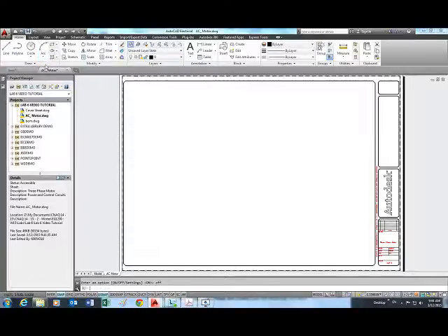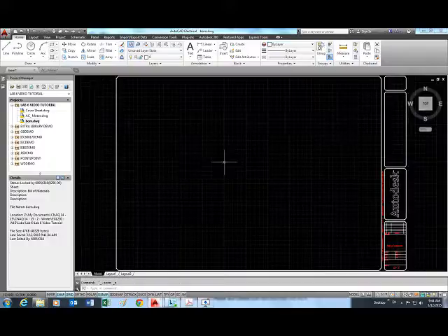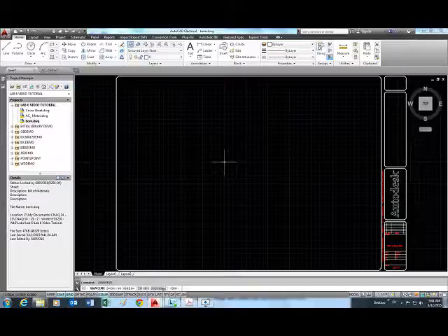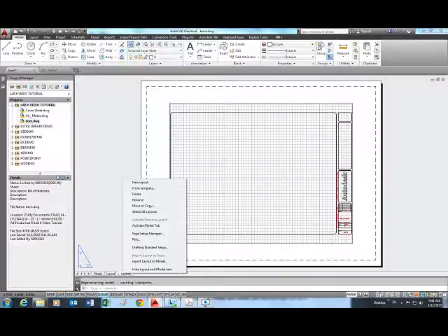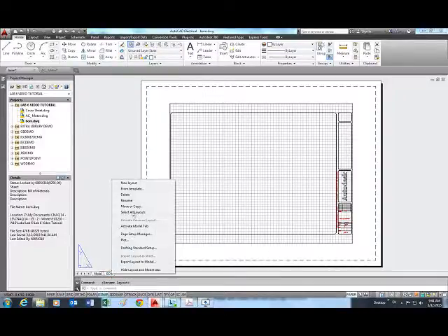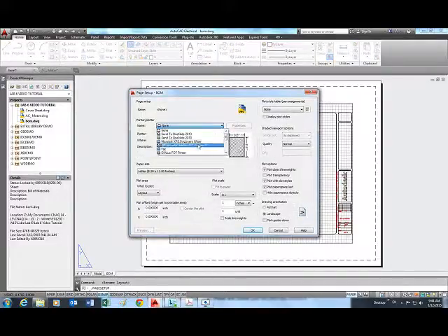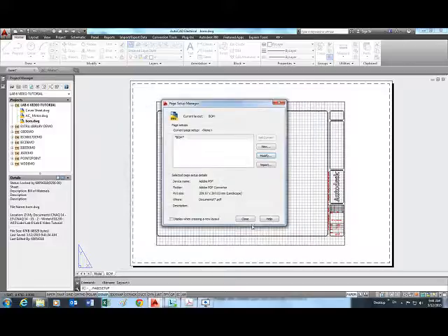So it's a good idea to save every so often to make sure that in case something goes wrong in AutoCAD that your work is not lost. Okay, let's go to BOM drawing, say nav cube, again off from the model tab, delete the extra layout tab. Let's call this BOM, enter, right click, page setup manager, modify, again PDF, Adobe PDF, A4 letter size, in landscape, and OK, close.